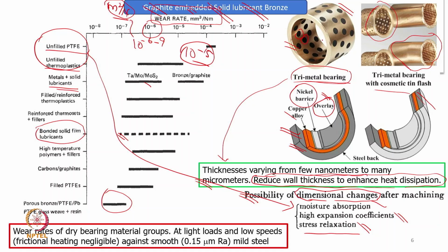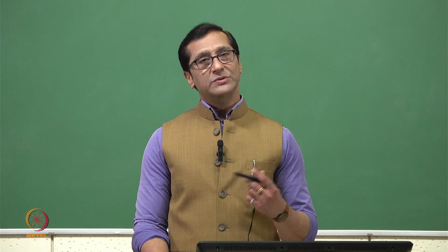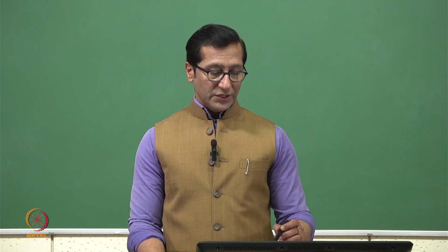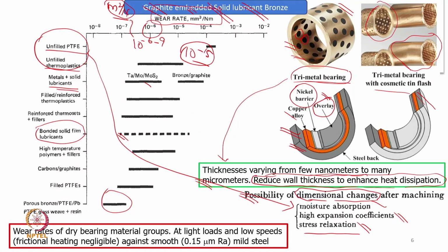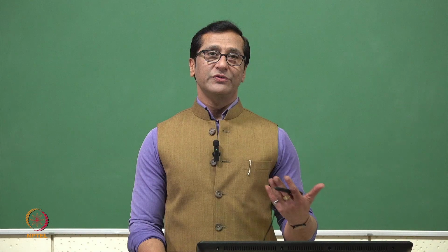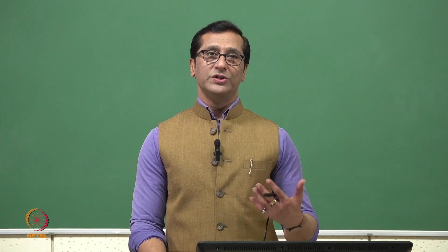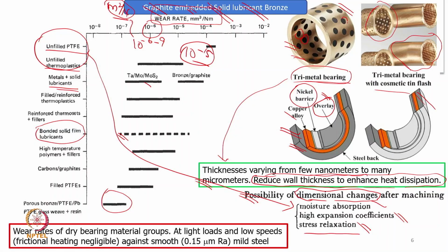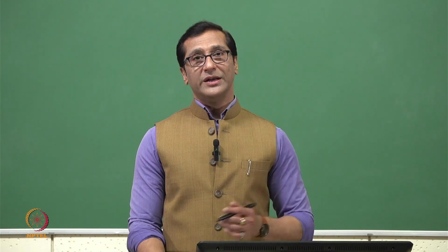Now these bearings also can be made as porous bearings, and in porous bearings we can really increase the liquid lubricant also, so it will give a very good result. That's why I'm mentioning that more and more technologies are coming and upgrading the bearing technology. Initially we were using only bronze bearings. Now there are porous bearings which have an impregnation with liquid lubricant, or it can be grease also. And here we are showing a picture of carbon graphite which has been embedded in this kind of holes. Those things will really change the bearing characteristics.